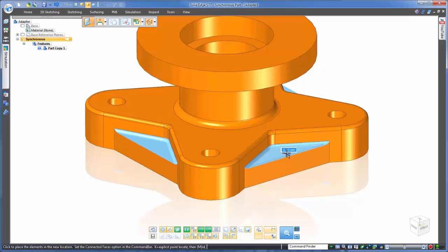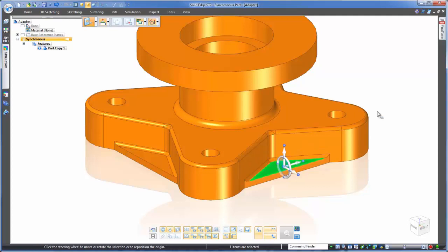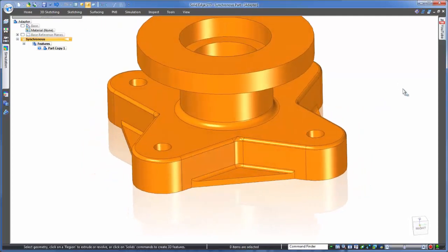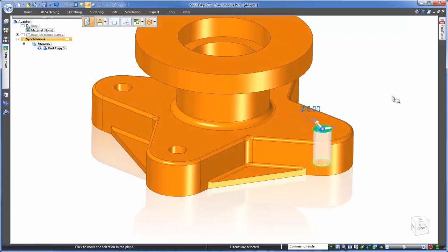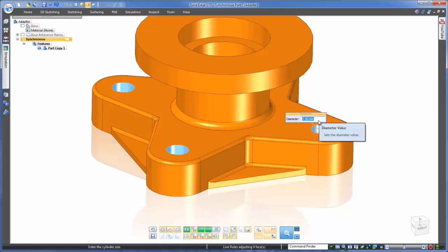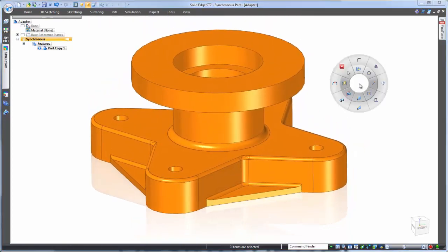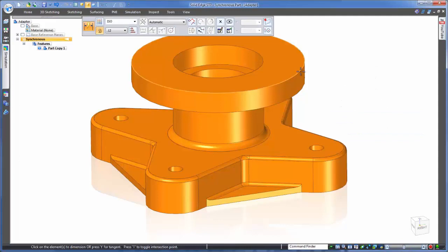Click on a face and drag, and notice how the other faces that are in line with this are moving too, just as if it was a feature in a history tree. But what if you prefer editing existing dimensions instead? Sure, just click a face and Solid Edge will give you the dimension of that feature on the fly, ready to edit. Again, notice the intelligence of all the other holes changing as if it was in a pattern. I know, it looks like magic.